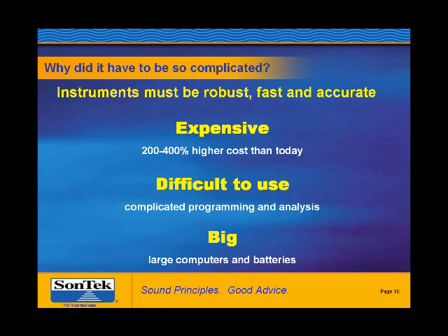So in order to properly measure waves and to be able to survive the waves themselves, instruments over the years have to have a few very key characteristics. Well, one is that they must be physically robust. In other words, be physically strong enough to survive the environment. They also must be able to sample their sensors fast enough. This typically means 1 to 2 times a second in general. They must also accurately measure the key parameters, such as currents and pressure.